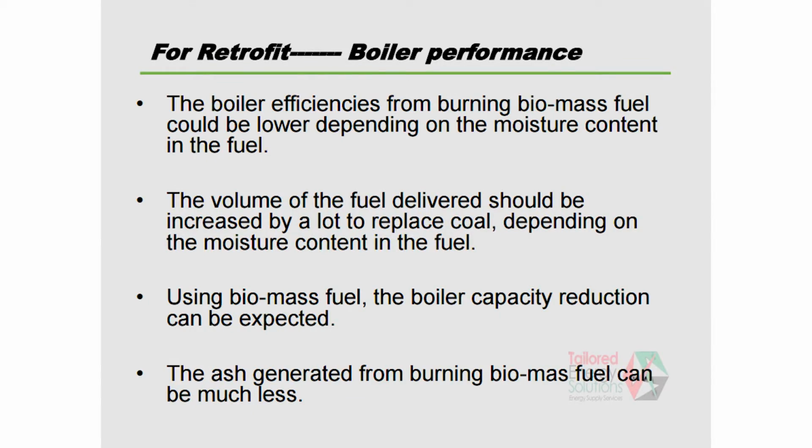On the boiler performance side, burning wood waste, the efficiency can be slightly lower, and you need to consider the delivery system, how much volume you need. And then you need to consider that capacity reduction could be the case. The ash generation from wood waste is going to be less anyway.